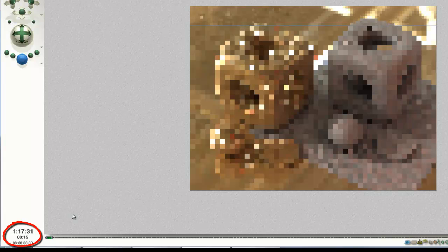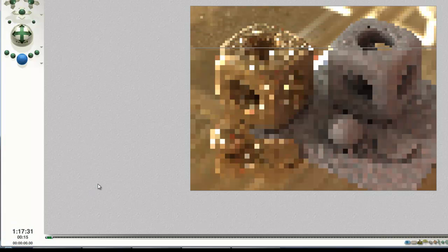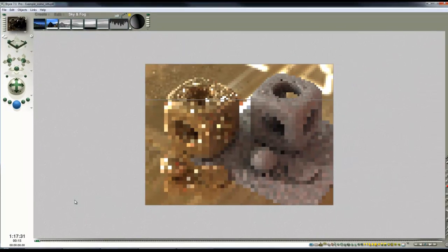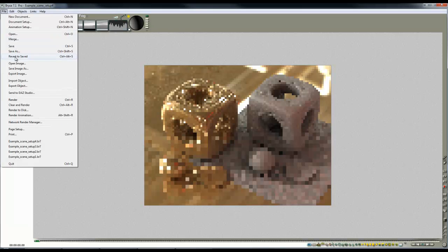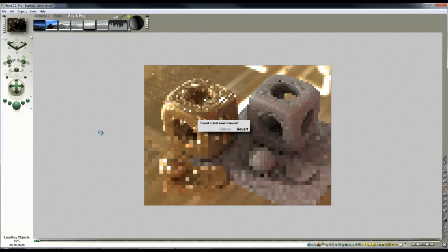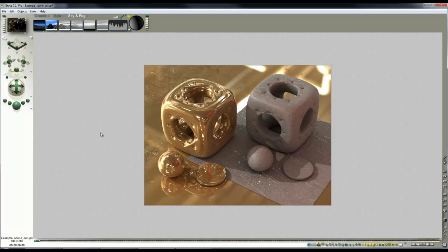There you go, 1 hour 17 minutes, so another 4 minutes in its estimation there to provide another premium effect, whereas if you're doing a regular render and you applied soft shadows to the sun, you would see a significant rise in render time because of the additional sampling it has to do. So if you've already gone to the extent of getting that sampling rate anyway, you may as well use whatever premium effects you want to use, because it's not going to make that much difference.